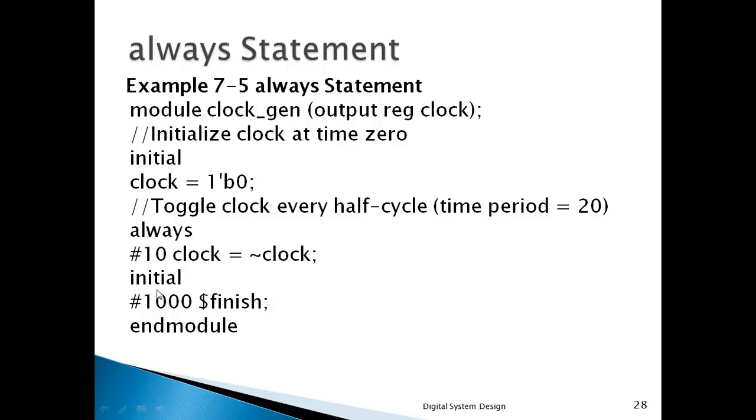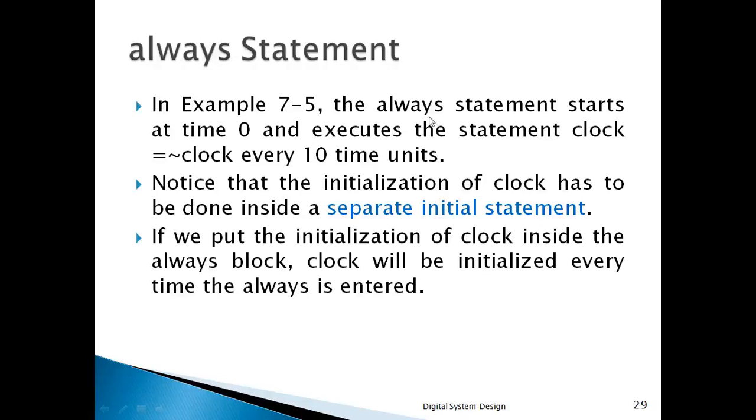Here this initial block explains that after 1000 time units this simulation will be ended. Now the explanation says the always statement starts at time 0 and executes the statement every 10 time units. Please note that the initialization of clock has to be done inside a separate initial statement.